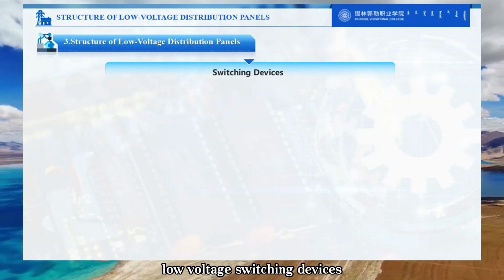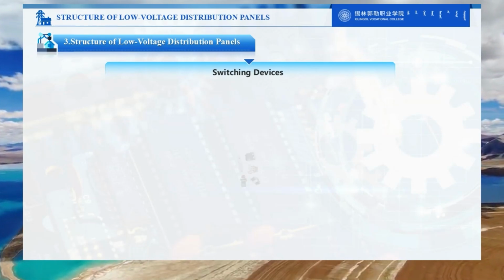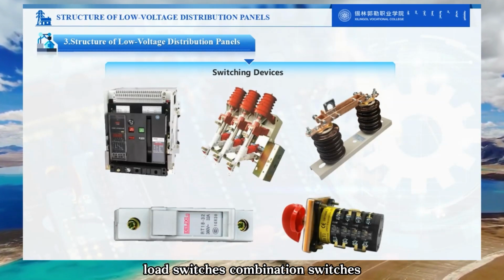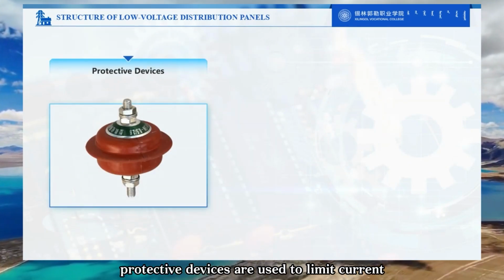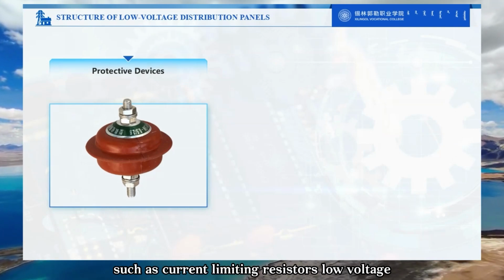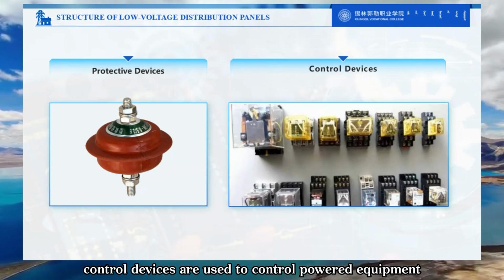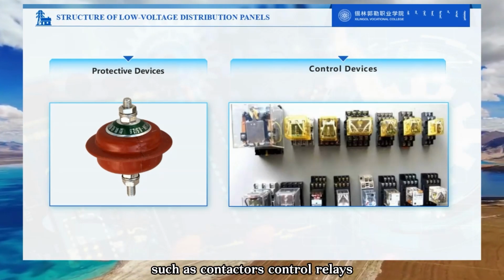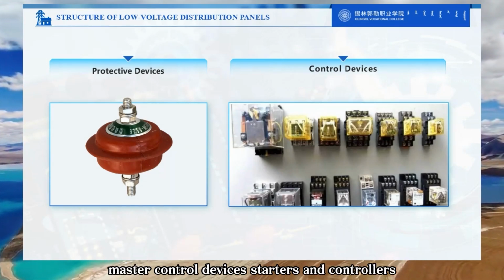Low-voltage switching devices are low-voltage electrical devices used to connect and disconnect circuits, such as low-voltage circuit breakers, load switches, combination switches, fuses, and knife switches. Protective devices are used to limit current and protect against overvoltage, such as current-limiting resistors, low-voltage surge arresters, and grounding grids. Control devices are used to control powered equipment to achieve the desired operating state, such as contactors, control relays, master control devices, starters, and controllers.